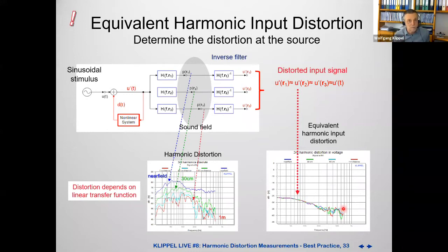And it's more meaningful. Why? Because 0 dB means the full voltage. Here, we are effectively at this point. That's more or less your generator voltage provided by the generator. And these are the distortions, D from T, added to the generator signal, minus 25 dB.